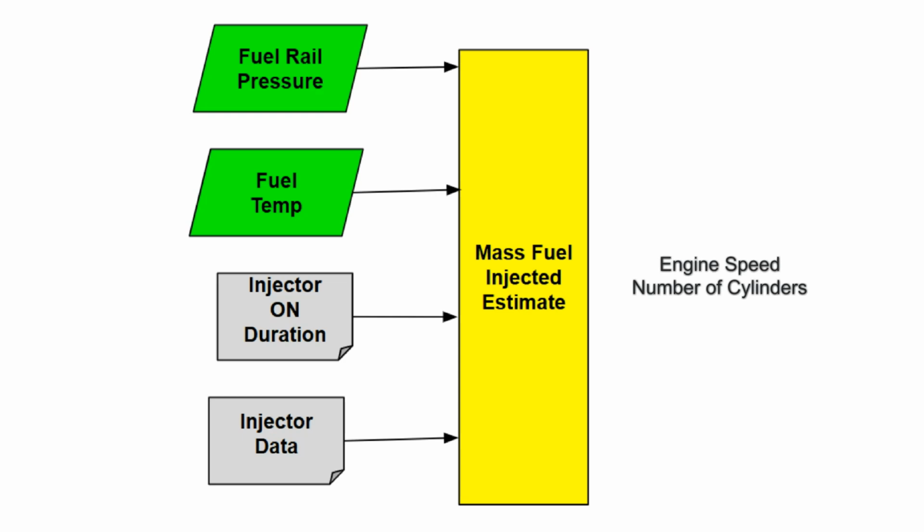Engine speed and constants such as the number of cylinders are used in the math model to convert the individual mass of fuel per injection event, such as milligrams per stroke, to what we'll call a mass fuel injected, the mass of the fuel injected, which we'll use in this case pounds per minute, just like the air flow. We can also use the metric equivalent, of course.